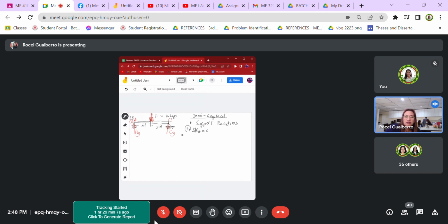Clockwise is positive. So, you have your force, F, times 5 inches, minus your CY, distance is 10 inches, equal to 0. So, we have now yung CY, you transpose that to the other side and substitute the value of F. So, this is 10 kips, 5 inches, is equal to positive CY times 10 inches. So, your CY therefore would be 50 over 10. So, that would be 5 kips. See our answer. This is 5 kips.